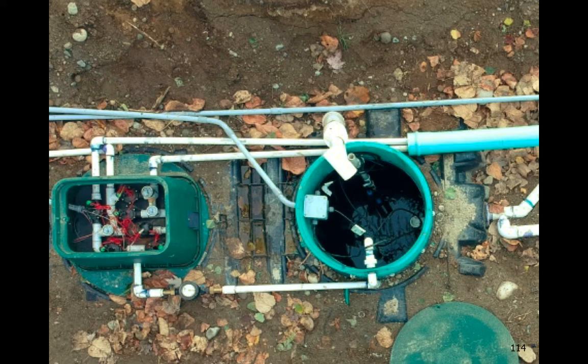And what this does is it gives us a real symmetrical, clean-looking installation where we'll have two tank openings with our Headworks in between, and the flow meter is between the pump and the Headworks. And this will allow us to measure, if we need to or want to, the flow, no matter what kind of function that we're providing or testing for. And then you'll see our to and from lines going to the low flow head off to the right, and our two tank line is heading off to the left.